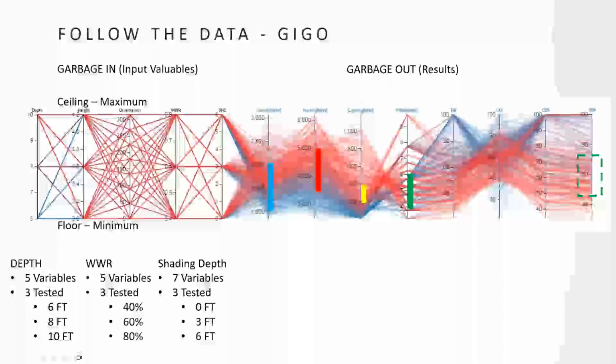And so basically what you need to be doing is applying your range. I showed you that earlier on the Autodesk Insight. What that means is basically this is our range. Our cooling can't be lower than 1,000 and it can't be greater than 2,000. We've worked with our engineer and that's what they've told us. Here it's 3,500 to 5,000 kilowatt hours. We don't want to use more than 5,000. The base operating of the system, if it's not occupied, would be 3,500 or something like that. Our lighting, you're a lighting expert, and I tell you, based off the technology and the lighting power allowance for IECC 2018, you can't go above 400. For the basic lighting you have to install to meet programming requirements, you're going to be using at least 200 kilowatt hours, somewhere in between. And you just basically go down the line and do that.